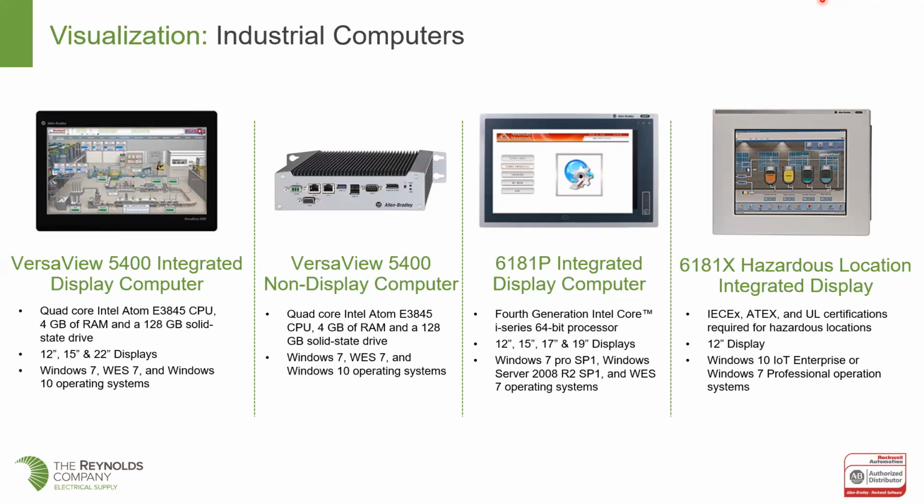The 6181 integrated display computers, a lot of times, would be a PanelView replacer if we want to run something with an OS in the background. We've often used these. And currently right now, our only integrated computer display is our 6181X. It's a fully integrated PC and display, and it is Class 1 Div 2.